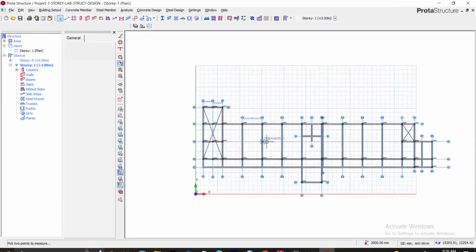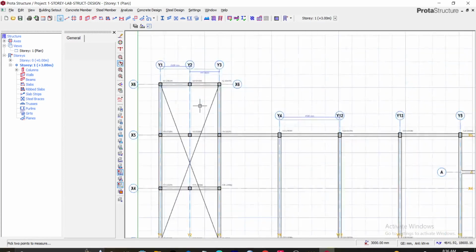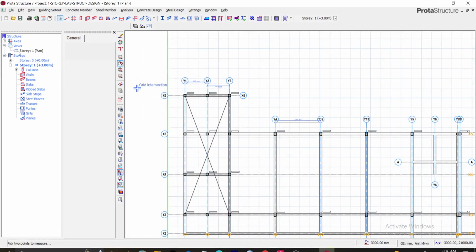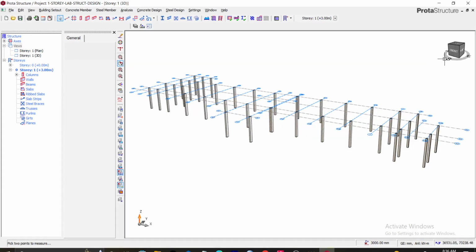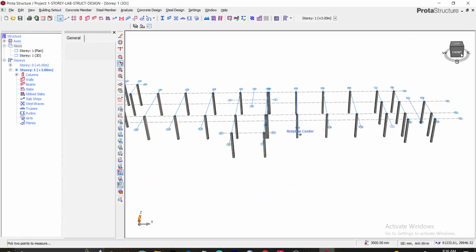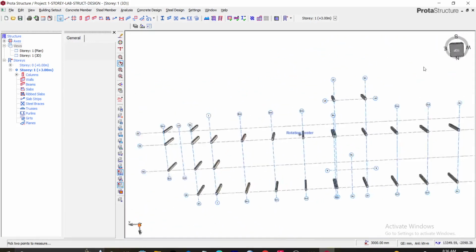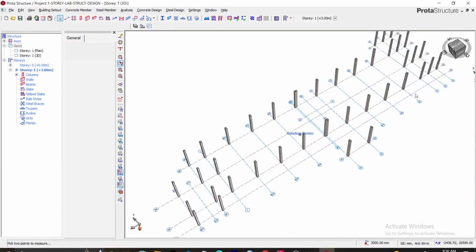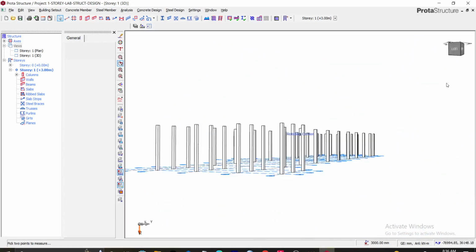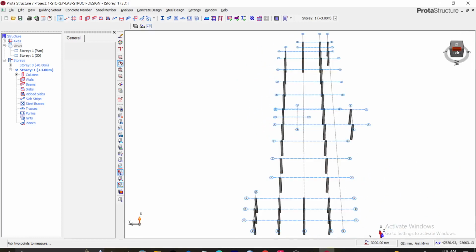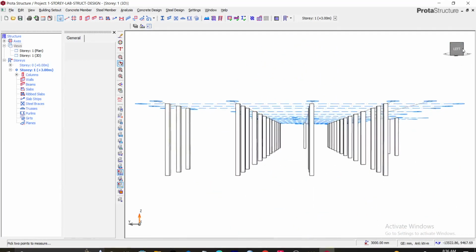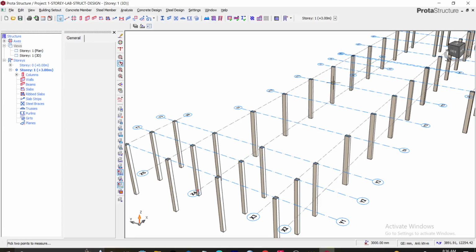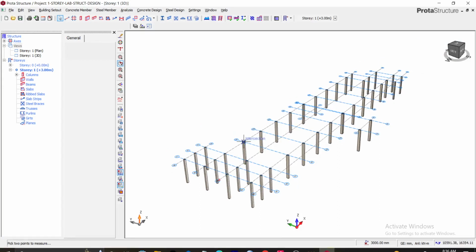In our next video, we'll see how to add beams, because now we already have the columns. If you come to 3D view, you can see those are your columns with the exact size the way they were in AutoCAD. What you are left with now is creating the subsequent stories of the building, and then you can start loading your beams. So you already have the columns, you're just adding beams and then adding loads, and then you do the analysis. Maybe you also model the roof. This is all about importing.